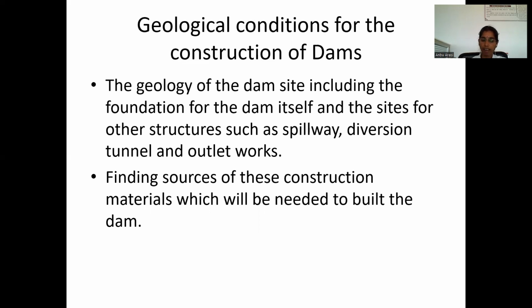Questions that need an answer include whether the dam foundation has sufficient strength and durability to support the type of dam proposed, whether the foundation is watertight, and if not, how much grouting will be required, and whether the spillway will require concrete lining. The geology of the area to be occupied by the reservoir once the dam is completed.